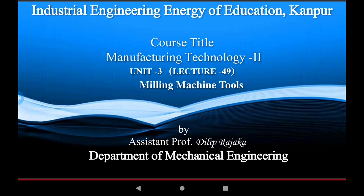Okay, in the last lecture we discussed the indexing of milling machines, the compounding of milling machines, and angular milling machines. Compound indexing uses a 40-tooth gear and worm shaft and worm gear for these machines, for the manufacturing operation and to generate continuous operations, and we solved some numerical problems on compound indexing of milling machines.